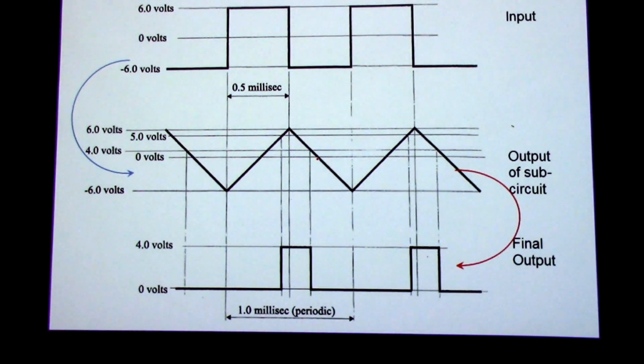Now here is the design goal. First, you have to use a square wave. That's the first stage. So you can get it from the FGen, no problem. Half millisecond, that means your time period is 1 millisecond and you have 1 kilohertz signal. And from that you have to generate a triangle, the triangular wave. So the easiest way to do is to integrate, like you have used an integrator before.